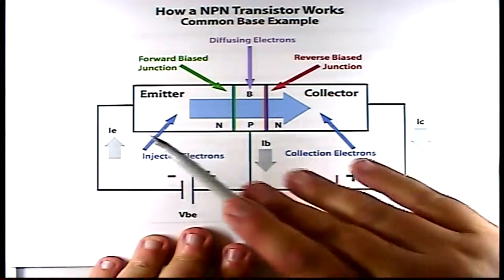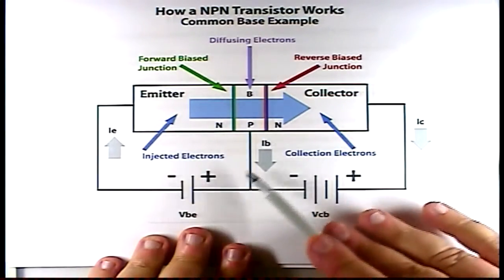The silicon transistor has to have a 0.7 volt forward bias for conduction. A germanium transistor has to have 0.3 volts for conduction. So we're saying this battery is putting out something higher than 0.7 volts, and that higher than 0.7 volts between here and here causes conduction.